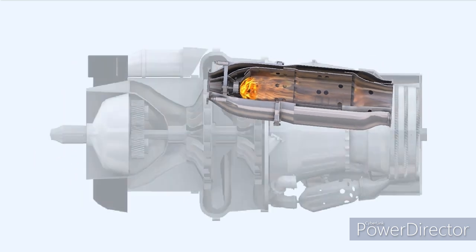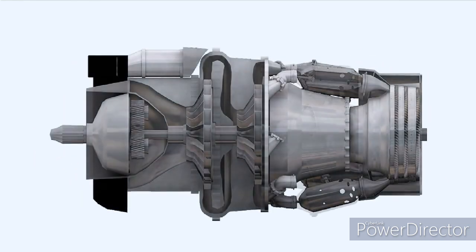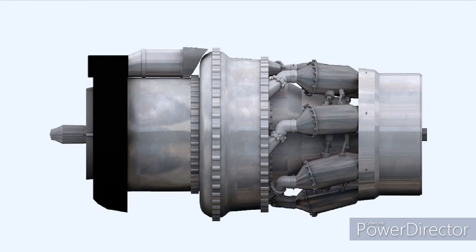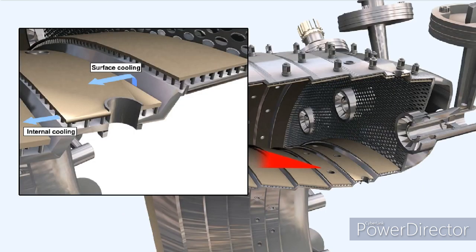The type of combustion chamber which we have used to illustrate the interaction of the flame and the cooling air is representative of those which would have been used in an early multiple combustion chamber system. Different methods of keeping the combustion chambers from overheating are used. Some flame tubes have ceramic-coated tiles fixed to a skin on their interior walls.